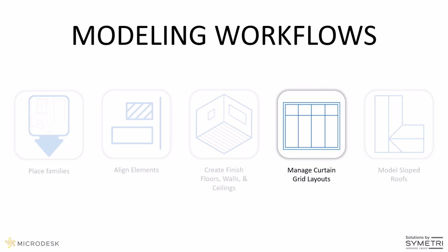to select the curtain grid because there's mullions in the way, there's curtain panels in the way, and then we have to rely on those automatic dimensions to specify how it's offset from one another or offset from the base. And if the automatic dimension didn't place it correctly, I've got to move it, or I have to create an elevation view where I actually add a dimension to get my curtain grid to move the way I want it to move. Especially if the design isn't consistent across the whole thing, right? We have different offsets, so I can't necessarily use the automatic one that's in the type parameters.